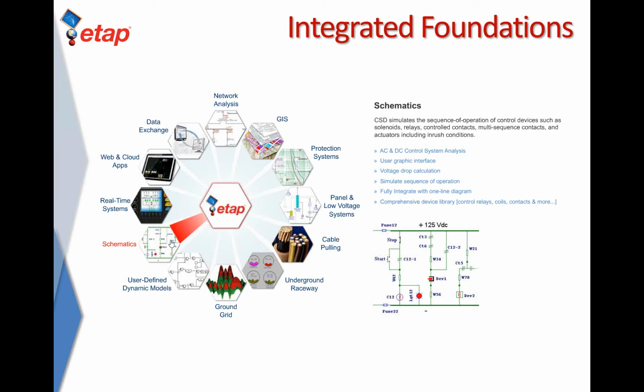As I mentioned, the ETAP network model that you use for design and planning can be migrated over to a real-time system where the model is connected with the real-time data, and we run various advanced applications on that model, such as predictive simulation, intelligent or fast load shedding, various energy management functions, as well as microgrid controllers.